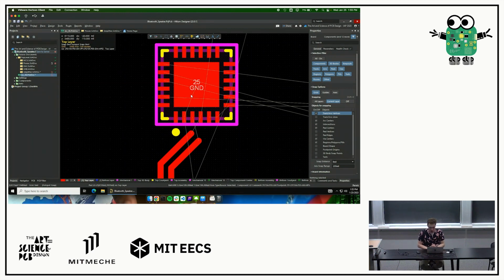For some other signals that are a lot slower, you might not actually care. The I2S signals between the DAC and the microcontroller are a slightly lower frequency, so it won't bite you as much, but you still generally don't want to route it through too many vias.